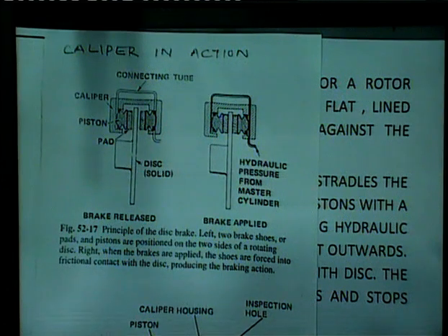gets hard and the braking is also hard. Though the brake lining is there, still the brake is not so effective. So, in this case the brake shoes have to be replaced.